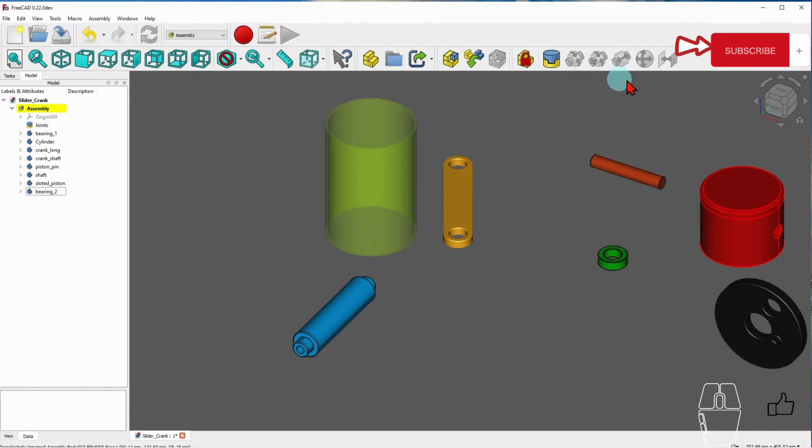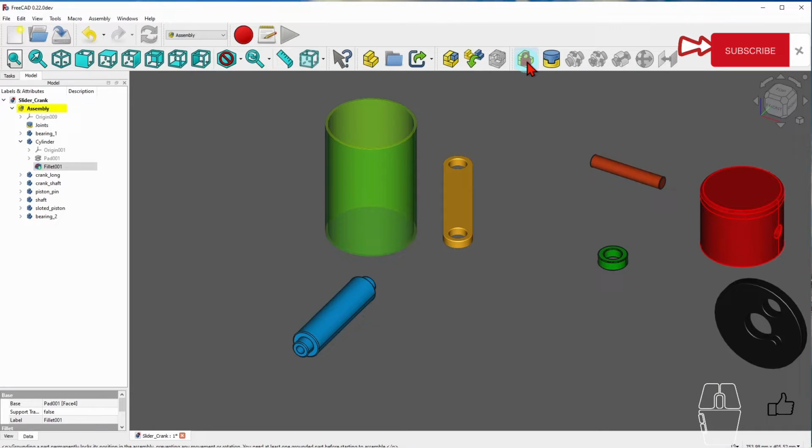Now these are all the items or the joints that you need to be using for this assembly. First thing you have to do is to start with grounding one component, a component that is stationary. Now the cylinder, as we know, is stationary, so you can ground it. How you do that is, select this component, and this is the button to ground this part. Ground means all degrees of freedom of this component are made 0.